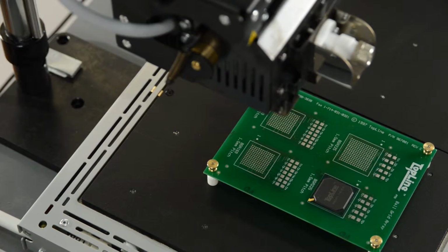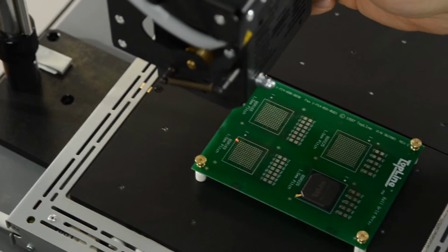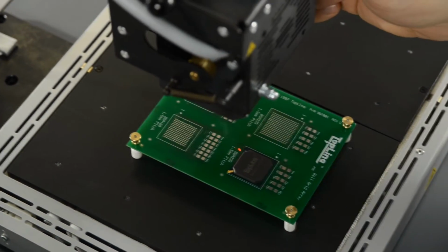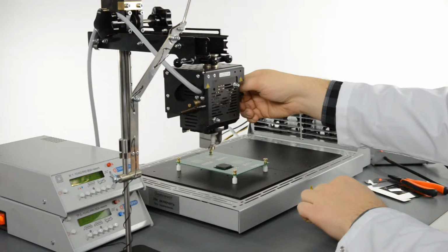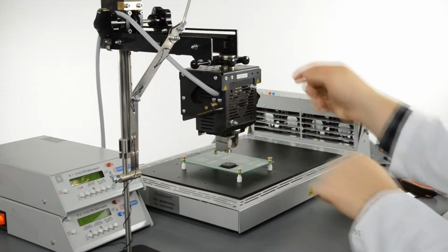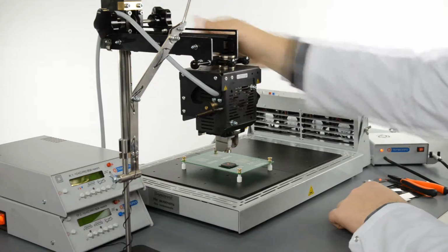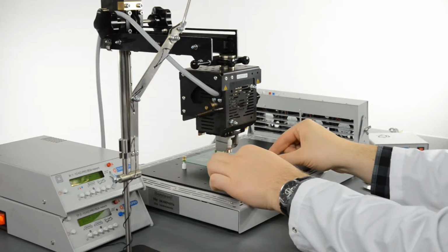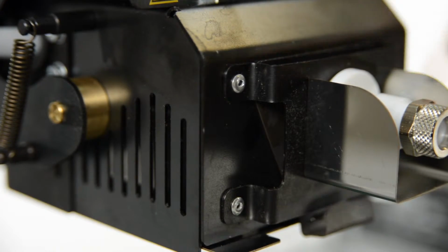Move the top heater into working position. To do this, turn the heater's head counterclockwise into the laser pointer position and move the laser dot to the center of the processed component by sliding the holder's arm and rotating it around the central shaft. After the laser dot is aimed at the center of the component, fix the holder arm by tightening the fixing nuts and turn the heater head into working position, turning it backward, clockwise.